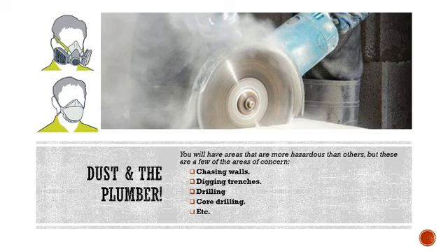And then we take a look at the actual PPE. If you look at the top left-hand corner, there are 2 different types of dust masks that we've put in there for you. This depends on the amount of dust and also the type of dust that you're going to be dealing with. For slightly more solid dust particles, like those from digging trenches, you could just use a normal dust mask.